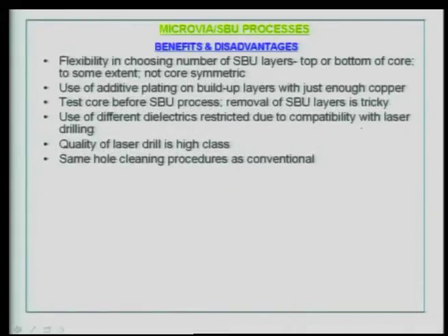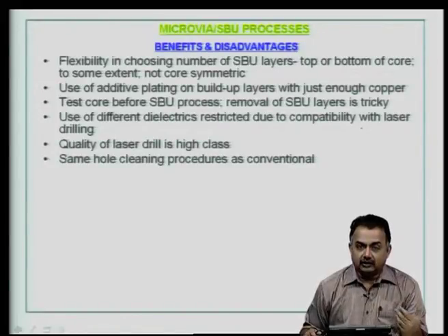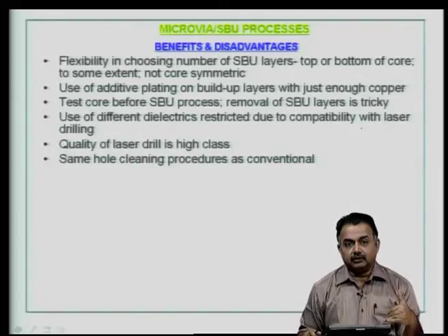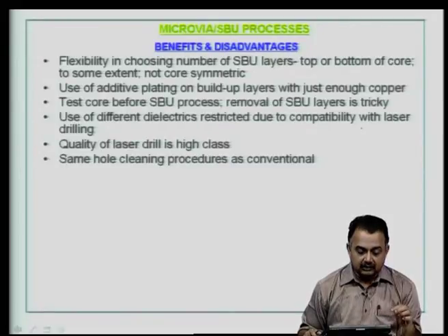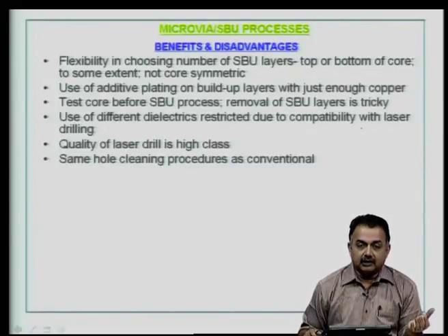Now, the benefits and disadvantages continue. We will discuss some more points. Now, in the case of a microvia SBU process, we have flexibility in choosing the number of SBU layers, either at the top or at the bottom of the core to some extent. This is not core symmetric. Compare this particular statement with the conventional multilayer boards.